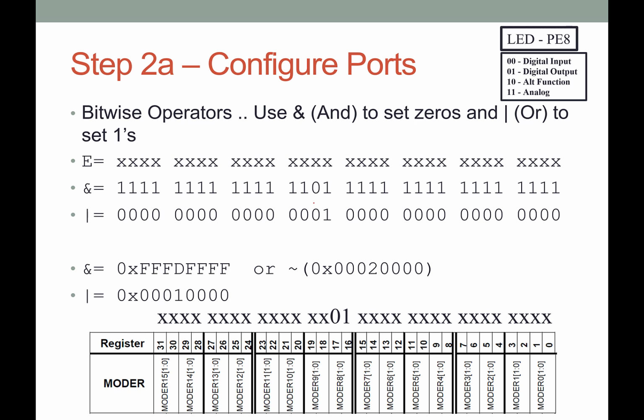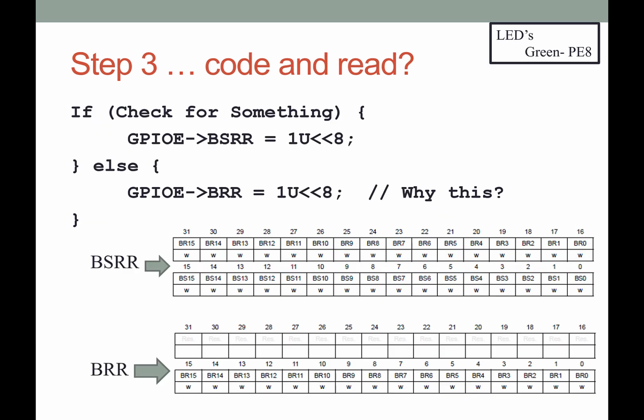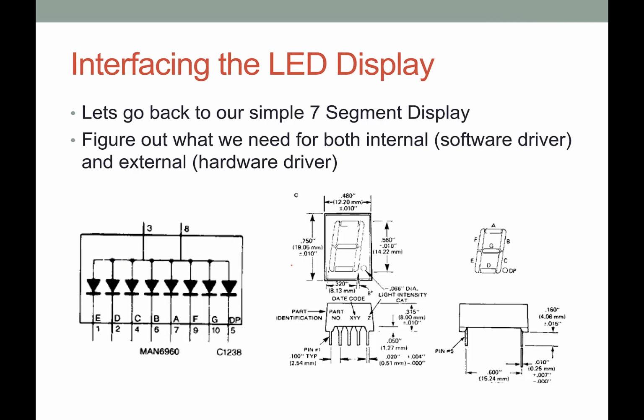except for this bit right here, because we wanted it to be a 0. And then we ORed it with having the 1 there, just in case it wasn't a 1 from that one. So our process to get a 0, 1 in here is done with this. And remember, we could have done it with this, but we actually did it with this mask, and then we complemented it. That's what we talked about doing before. So then we talked about the bit set and reset function, so we did that before last week, so I don't really have to go over that again.